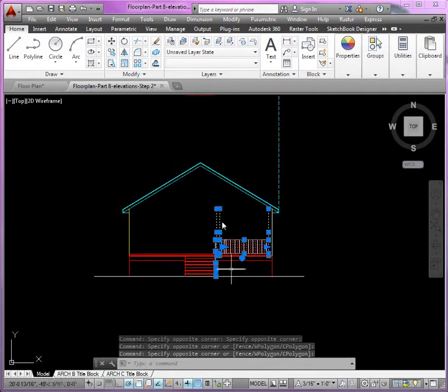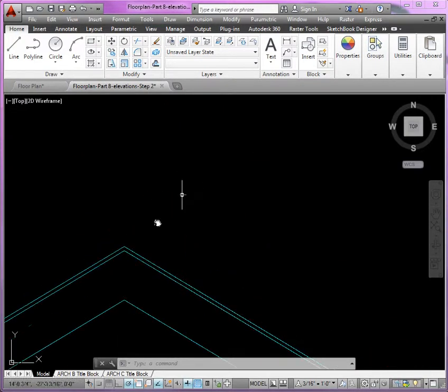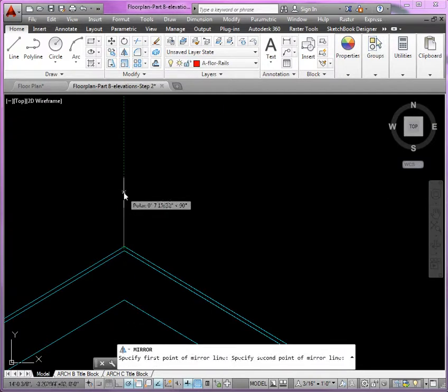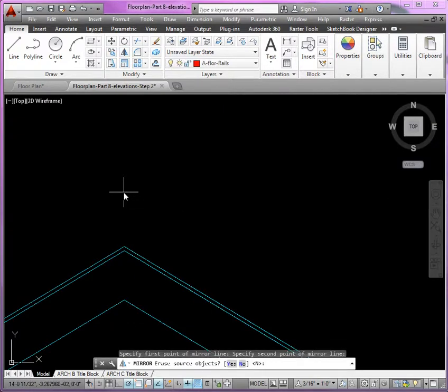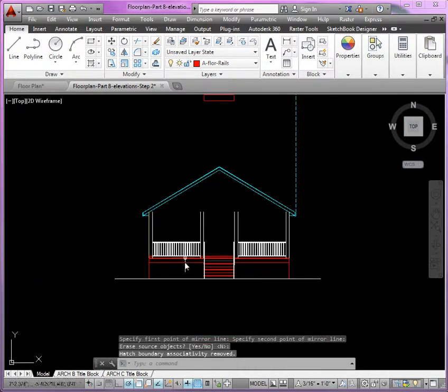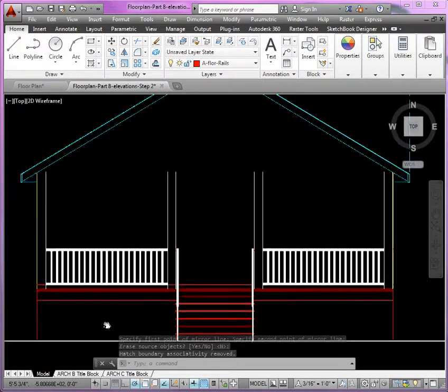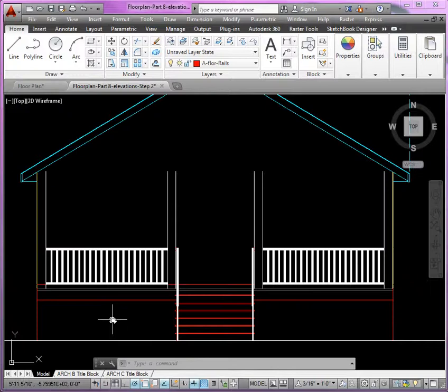Now I'm selecting everything here so I can then use, let's say, the midpoint here, right, to mirror everything back to the other side. So I'm just using those 2 points that I selected right now to make a mirror copy, right, and that's how I get the other side. Now as we proceed, obviously we're missing the windows and the door, but that's all that's left, and also our attic vent. And just before we do that, let's go back to the column layer, and we'll go ahead and draw in the 2 lines that represent the beam.